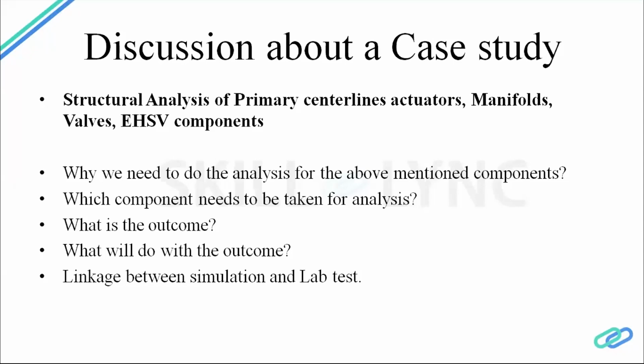Once you have done that, the meshing part is also as important as the first stage. Whenever you mesh in a proper manner, the result will be okay. Again, there will be issues with point loads because of wrong meshing or wrong methodology, which lead to wrong results, and again you lose time and energy of running.